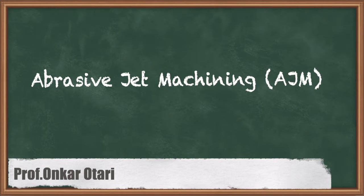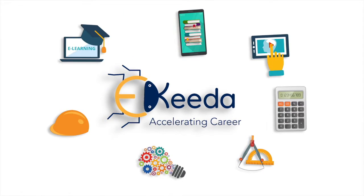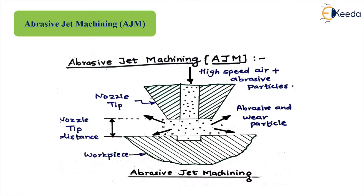Now let us start with the next non-traditional machining process, that is abrasive jet machining, AJM. You can see here in the diagram, this is the nozzle tip, this is your workpiece, and through this nozzle the high speed air along with the abrasive particles are moving, and they are impinging on this work surface and causing the removal of the material from the workpiece. Okay, so in AJM, the material removal takes place because of impingement of the fine abrasive particles onto the work surface, and the particles are moving with the speed of air or gas stream or jet.